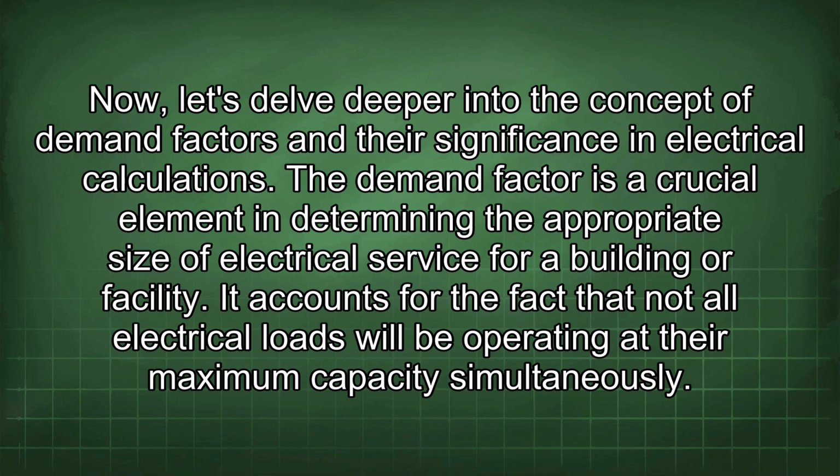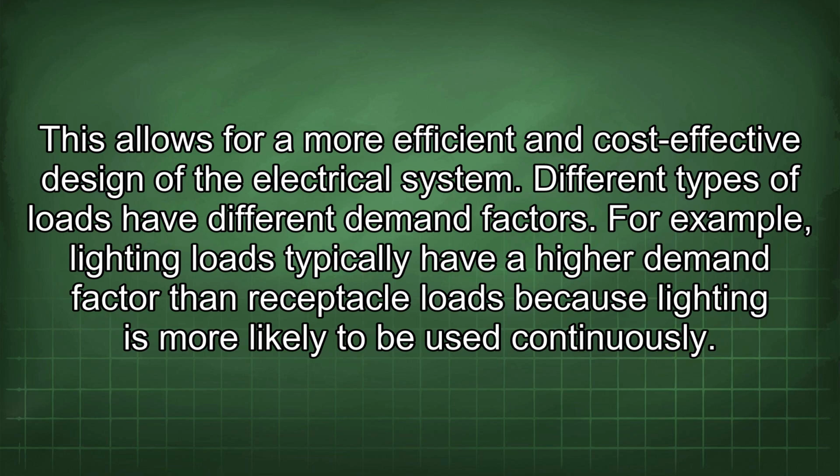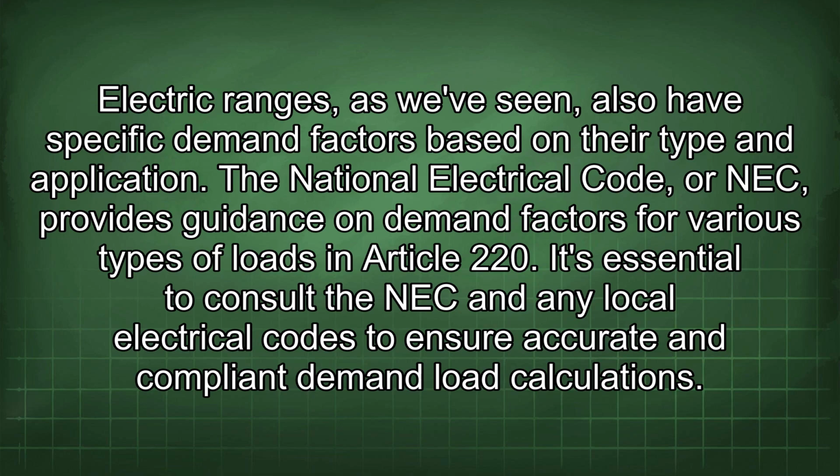Now, let's delve deeper into the concept of demand factors and their significance in electrical calculations. The demand factor is a crucial element in determining the appropriate size of electrical service for a building or facility. It accounts for the fact that not all electrical loads will be operating at their maximum capacity simultaneously. This allows for a more efficient and cost-effective design of the electrical system. Different types of loads have different demand factors. For example, lighting loads typically have a higher demand factor than receptacle loads because lighting is more likely to be used continuously. Electric ranges, as we've seen, also have specific demand factors based on their type and application.